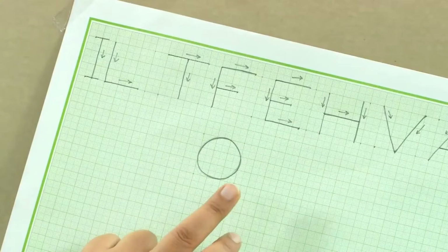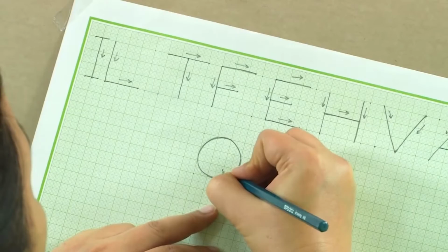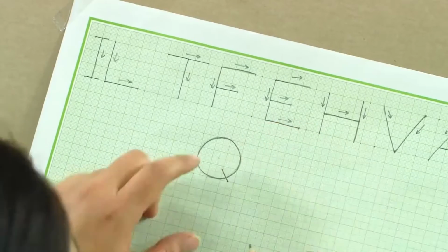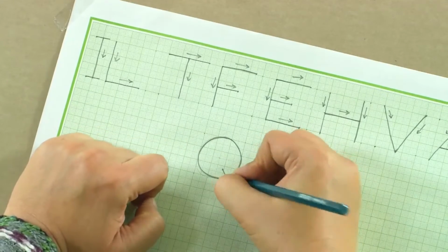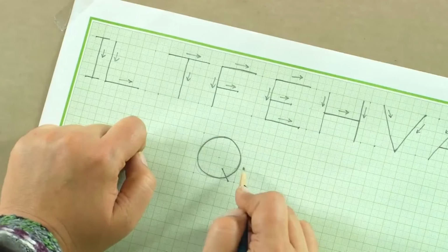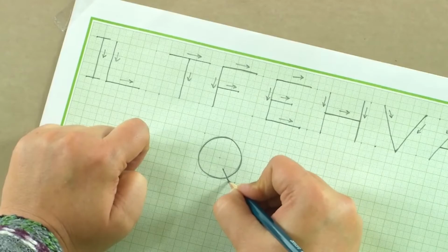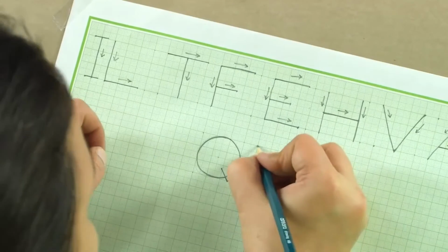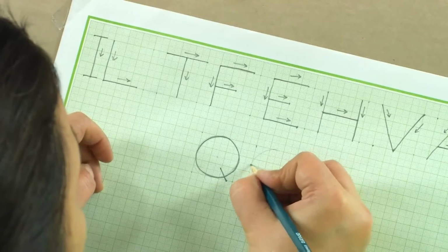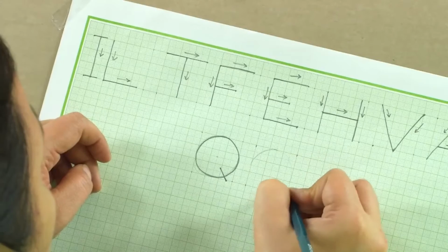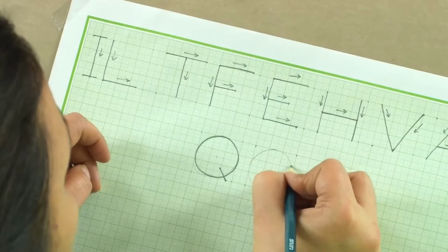If you have to make a Q, so what we do is we make a line joining the center with a unit recessed here, that is Q out of O. So, the O is just a circle, Q is a circle with this line joining center to a 1 unit recess. In case we have to do a C, it is again out of the circle, the same circle. Once you have practiced enough, you would not be needing to draw these guides.